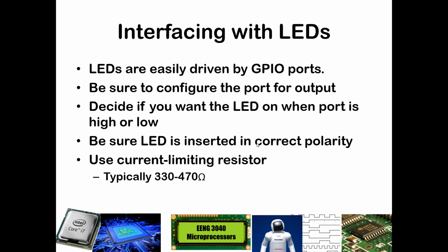It is important to note that LEDs are polarized devices. So as we indicated previously, LEDs can operate in the forward or reverse bias region. And if you put in your LED backwards, when you mean for it to turn on, it's going to end up being reverse biased and vice versa. And so you want to make sure that it is connected correctly. And so looking for the cathode and the anode, typically on an LED, if you just buy a pack of them, one leg is longer than the other. And so you want current to go in the long leg and out the short leg. And that is the typical orientation. So the long leg you can think of as being on the flat base of the triangle, and the short leg being on the tip, the point of the triangle, as you think of an LED in a schematic.